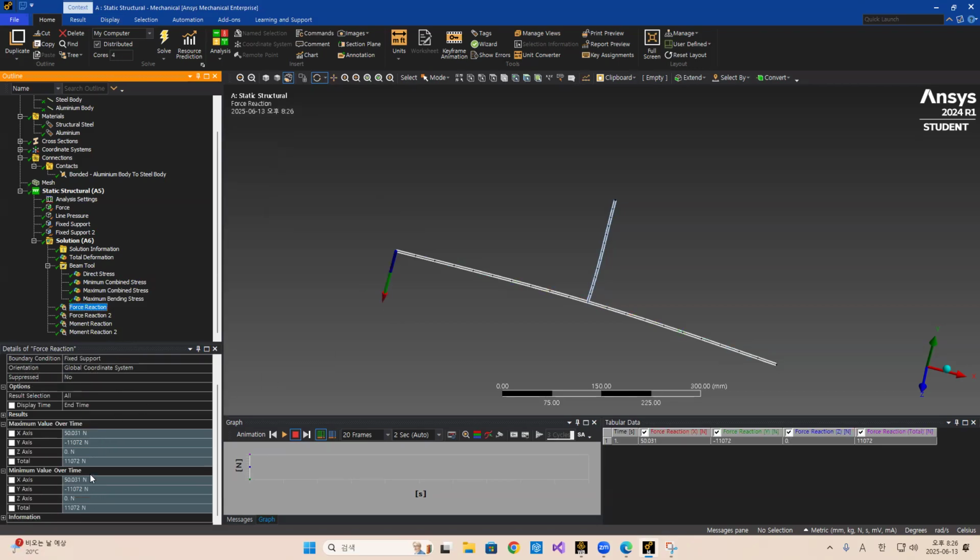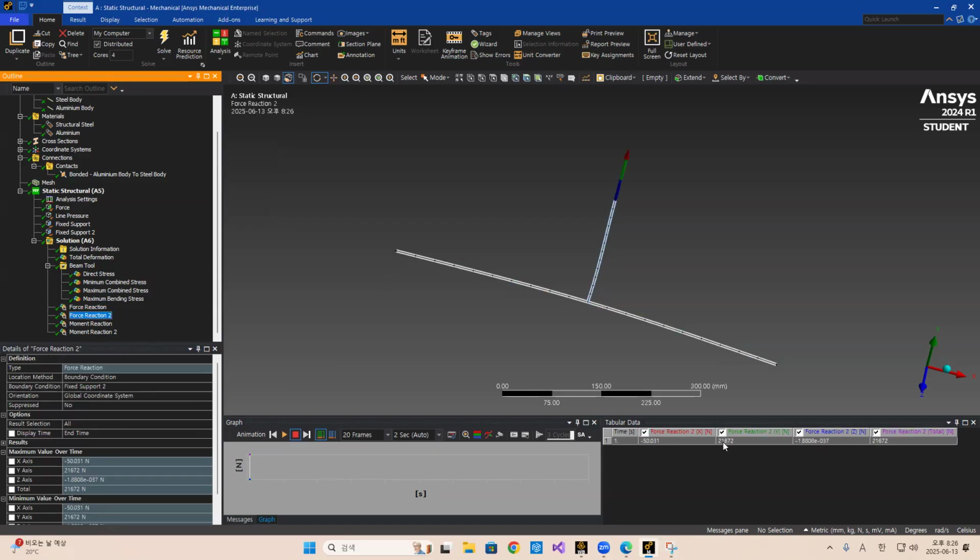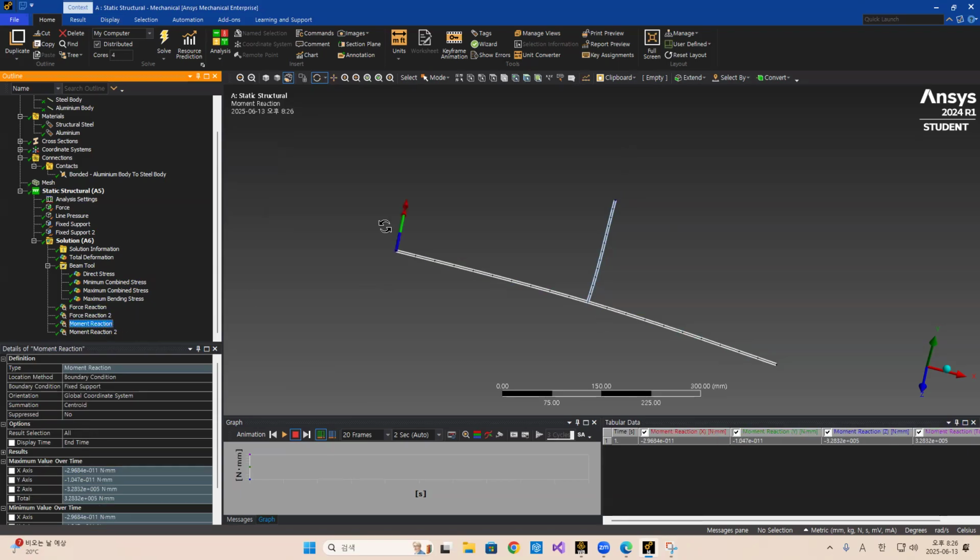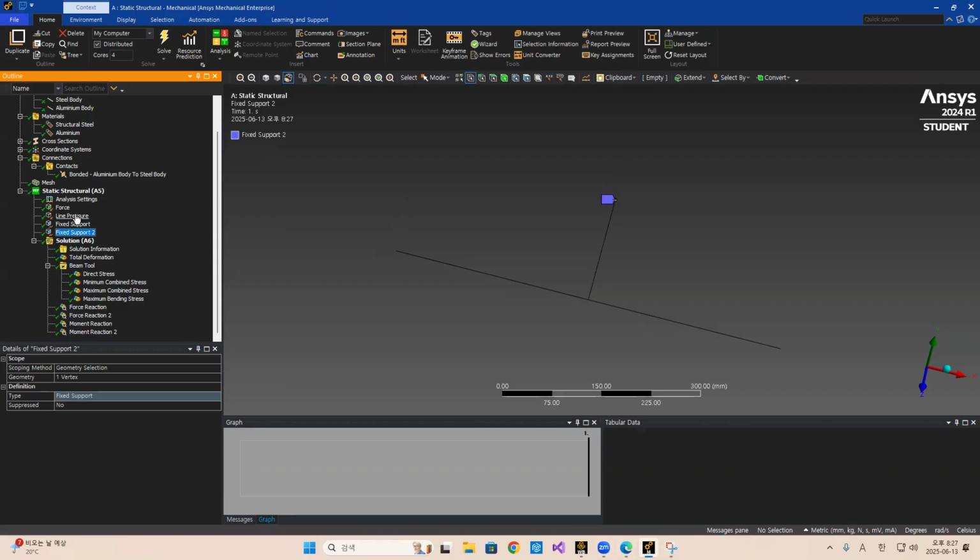The reaction forces also change. For the pinned joint we had minus 10,000, but here it is 11,000 or something, and here 20,000 something. Also we have a moment reaction here, 32,000 something, E5 meaning 320,000. Same here, we also have a moment reaction about the z axis, 3325. So those are the different things, a small change in the answer.